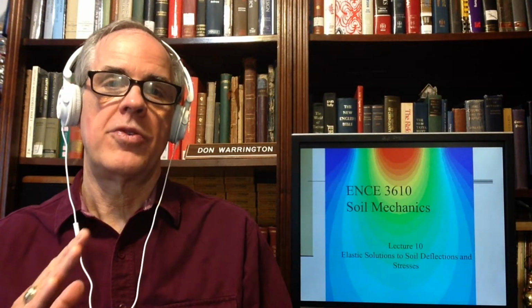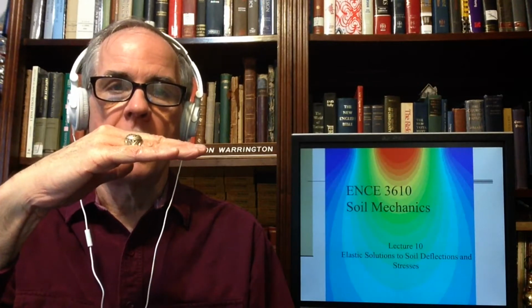What that means is that we start with zero, we go up in an elastic way to a certain point, at which point we say it fails, and then it will take no further stress. It reaches some maximum stress and then it takes none more. It just deforms. It doesn't increase the stress resistance. It won't take any more stress. That's what we're going to assume, and that's going to govern how we approach different problems.